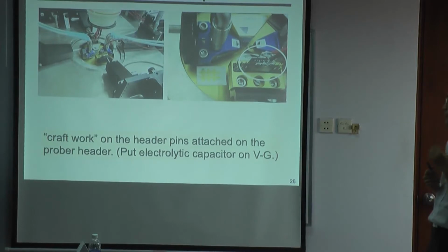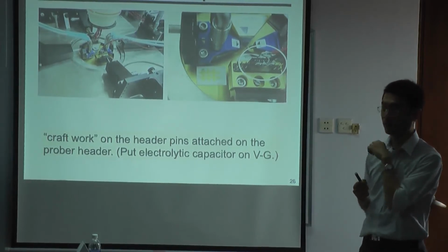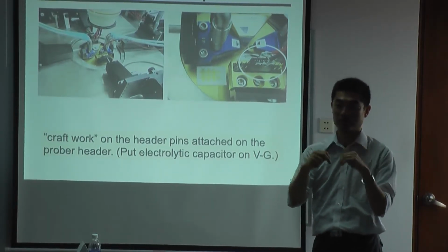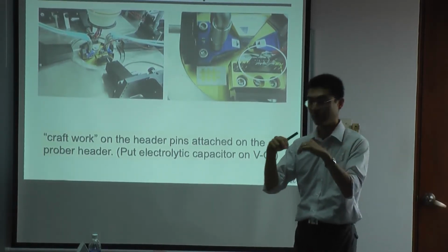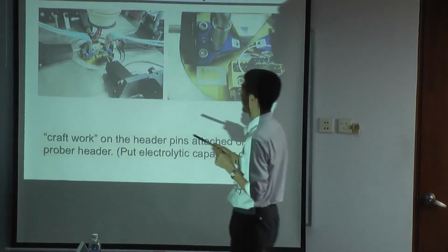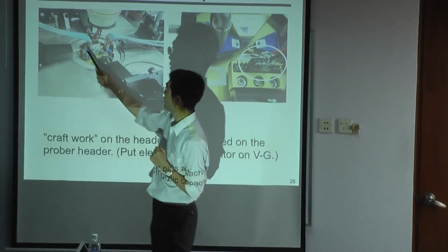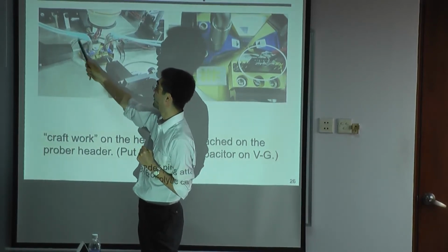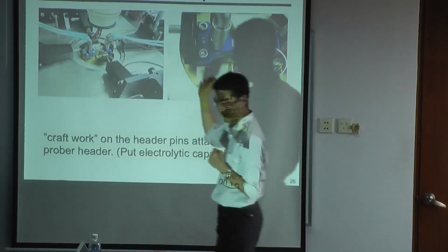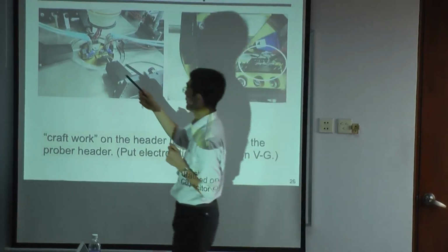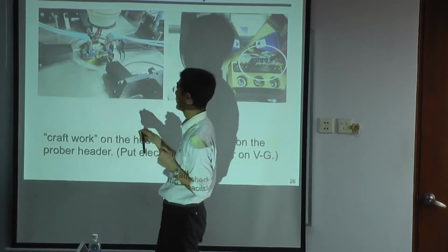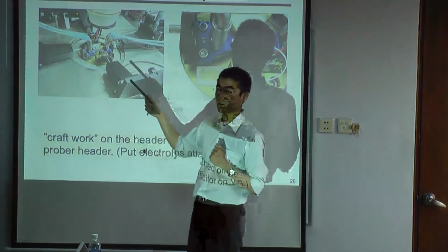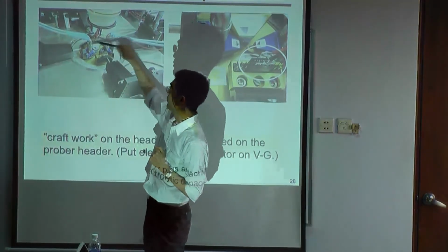And this is another example. This is a very high-speed measurement. So we directly probe on the chip. We don't assemble the package. Here, this is the picture. And I don't remember the signals, but we have two inputs and two outputs. There are two high-speed inputs and two high-speed outputs. And other control signals for power supply are supplied from these two probes.